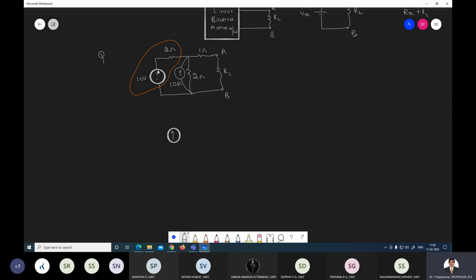Here it is minus plus, therefore you have to write the direction like this. If it is minus plus, then you write downward; the direction should change. Now in this case, I is equal to V by R. V is 10 and R is 2, therefore it is 5 amps. And whatever the resistance of 2 ohms, that becomes parallel.